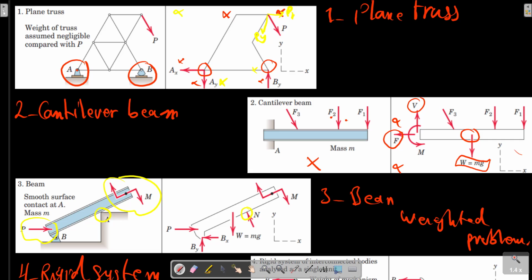The isolation of the mechanical system under consideration is a crucial step in the formulation of the mathematical model. The most important aspect to the correct construction of the all-important free body diagram is the clear-cut and unambiguous decision as to what is included and what is excluded.